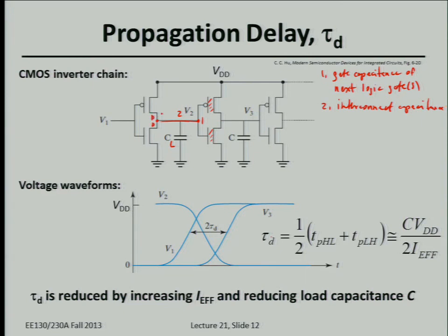So you need to have some kind of metal wire running to physically contact the drain regions, and then connect it to the gate electrodes of the next stage. And the wire runs over the silicon substrate, so there's some capacitance. There's some insulating material, of course, between the wire and the silicon substrate, but there's capacitance there. So that's good. One final source of capacitance, small signal capacitance. Yes, Justin? That's right. So it's junction capacitance. So it's the drain.